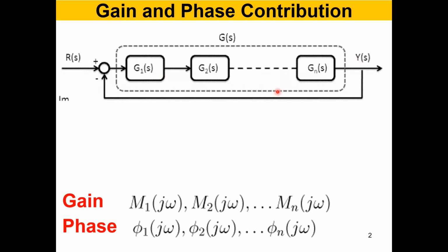And then if the response within the frequency range of interest is satisfied, then we are happy, right? And we conclude that, okay, fine, this loop is ready, it is good enough, it will do the job. And of course, we are concerned with a certain bandwidth, that is frequencies from 0 to some frequency.